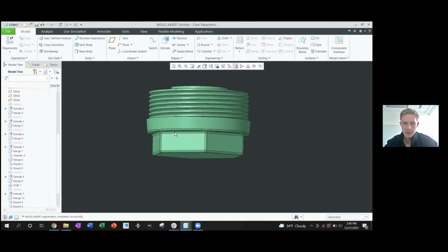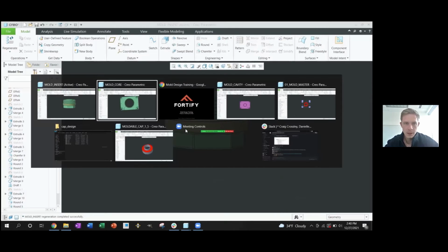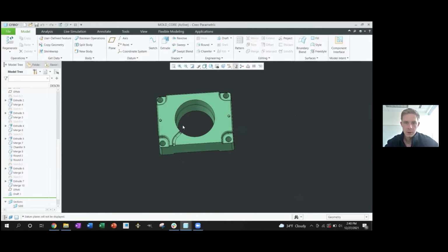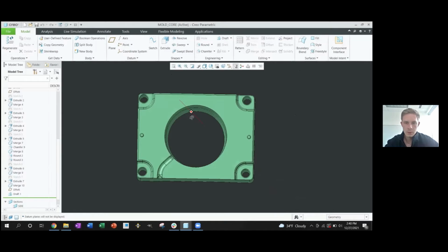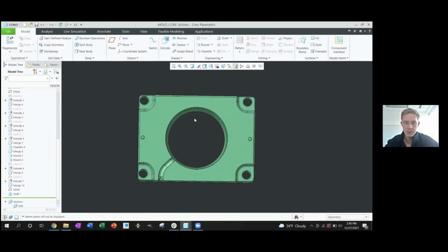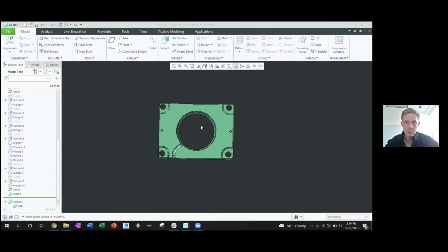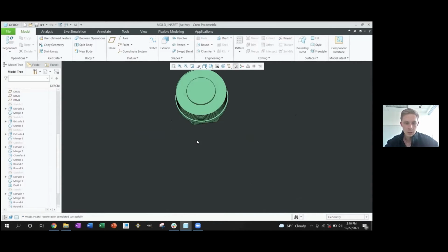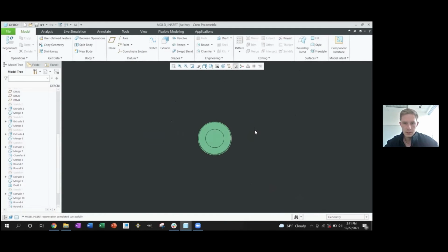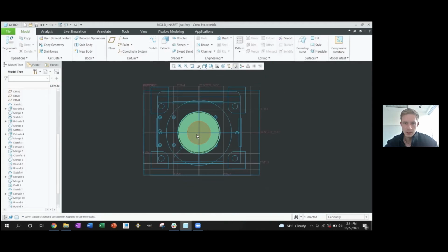We've broken the sharp edges on this insert. If we come back to our mold core itself, it's going to slot nicely into this core, but we have no orientation for this insert. So what we're going to do here is create a key feature for this insert so that every single time we put it into place, it's going to properly fit. So take a front view of this insert, show our sketches, show our planes.